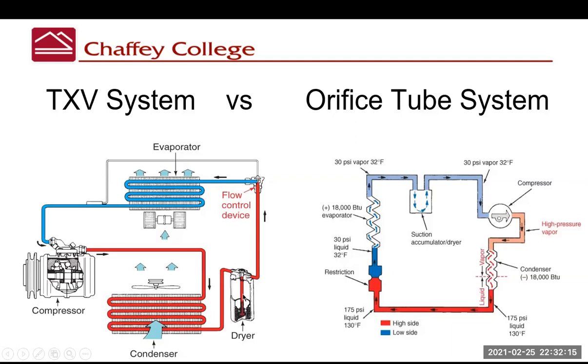causes the moisture to come out of the refrigerant. Refrigerants, they don't like water. So if you have moisture in your refrigerant, things can freeze up. So this takes the moisture out of the refrigerant with what's called a desiccant bag. We'll talk more about that later, but that's what it is.